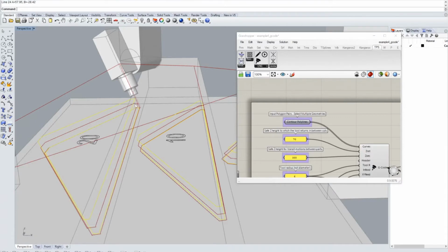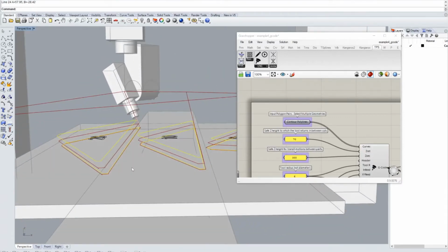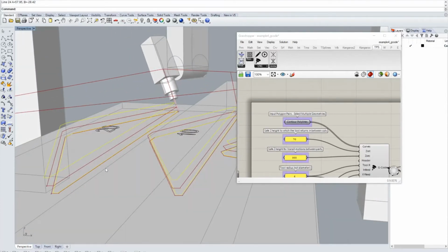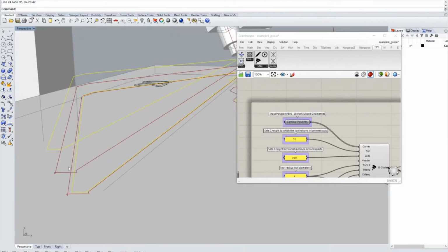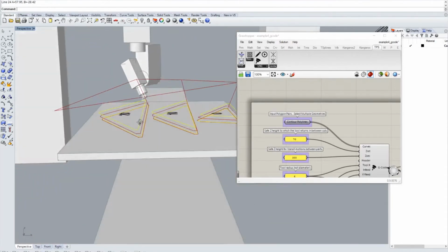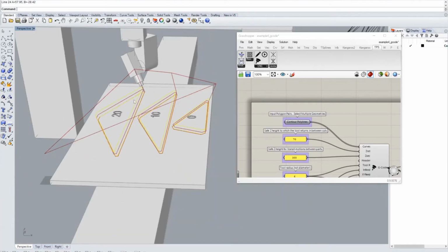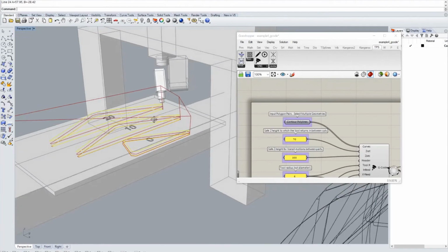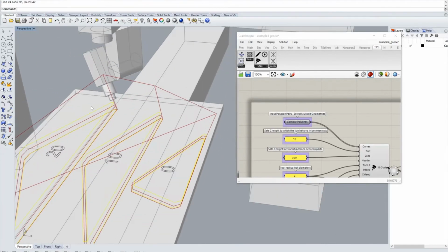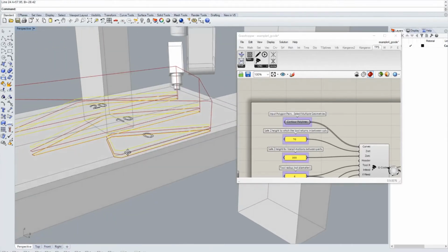So this is basically the path that this tool is going to go when it cuts these parts out of the plate. And if you look at the details, there are some slightly more complex things happening because this is all oblique cutting, 5-axis cutting. Then there is some points where it actually has to lift off from one part to another part. And in some cases there are also some parts during the cutting of one part where it has to lift off and reorient. We are not having this here right now.